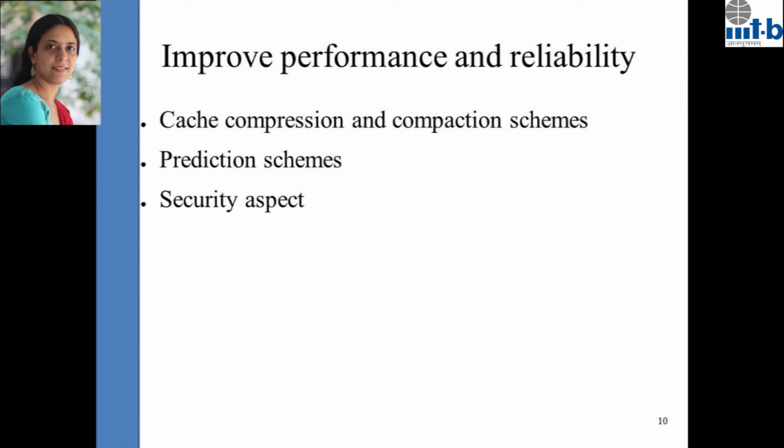Correct. So usually the trade-off is based on the application that you're targeting. For example, if you're trying to target a server kind of system, a high-end system, then you want more cores, you want to process more, and you also want higher cache. And if you're looking at, say, a mobile application or a gaming application, again the target is different. So usually they play around with all of these numbers and come to a conclusion as to how many cores can fit into that die and how much cache.